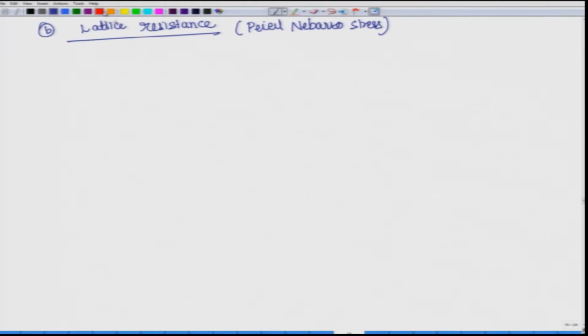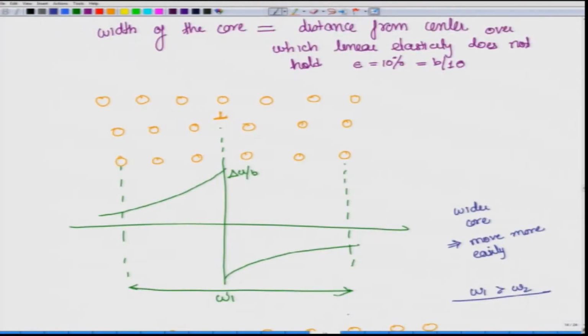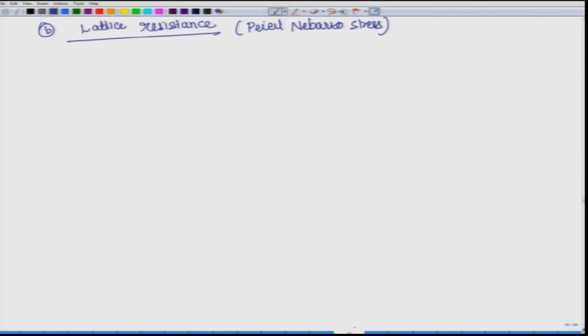Now, if you remember again, if we go back to our dislocations over here. So, this is the dislocation core. If it has to move from this point to this point, this particular layer of atoms has to now shift to the left, and this one which is a hanging one will get connected, and this will become the hanging one. Therefore, there is a kind of motion that has to take place from one connected column to another disconnected column, or one disconnected column to another disconnected column, and this would look more like this.